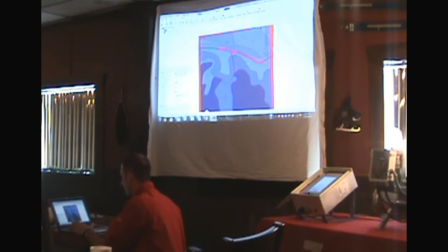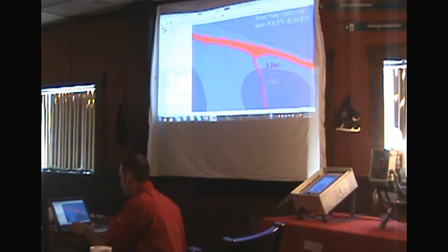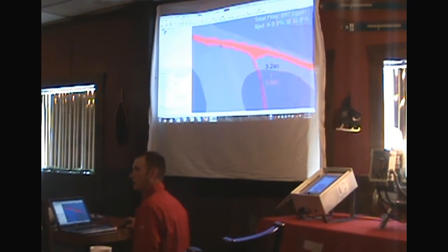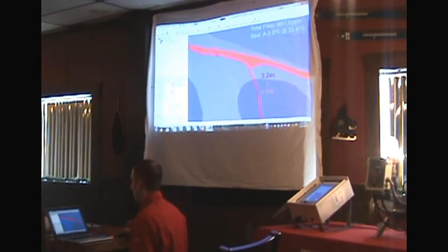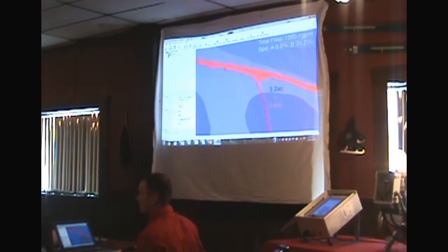One thing that I always want to point out is there's a difference between an avoidance layer and a 0% rate. If you see here, this is an avoidance layer. So anytime that one sprinkler is going to throw any water on that polygon, it's going to be dry. Okay? If this was a 0%, it would contour into it.